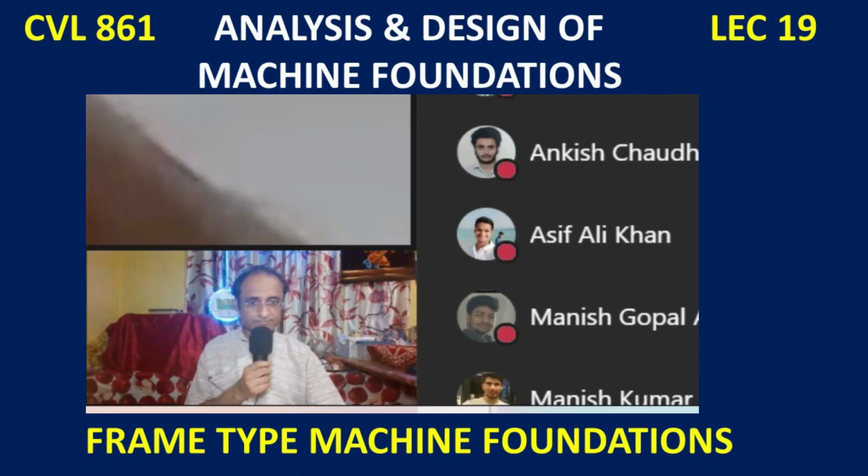Sir, why are we not considering damping in free vibration analysis for calculation of natural frequency? Free vibration analysis is like that only. We don't consider the damping. It's undamped free vibration analysis. The mode shapes etc. are for the undamped condition. We ignore damping.